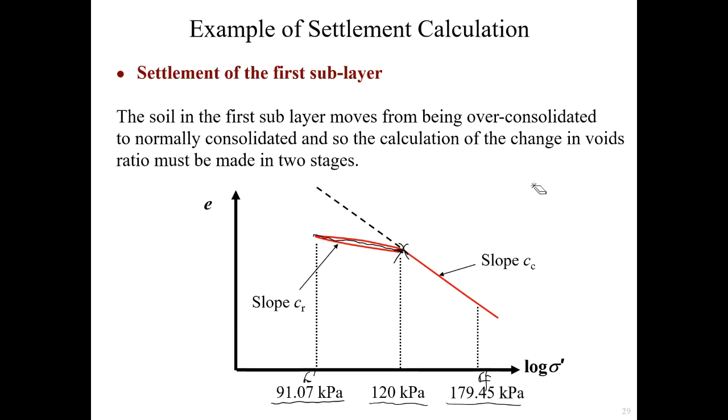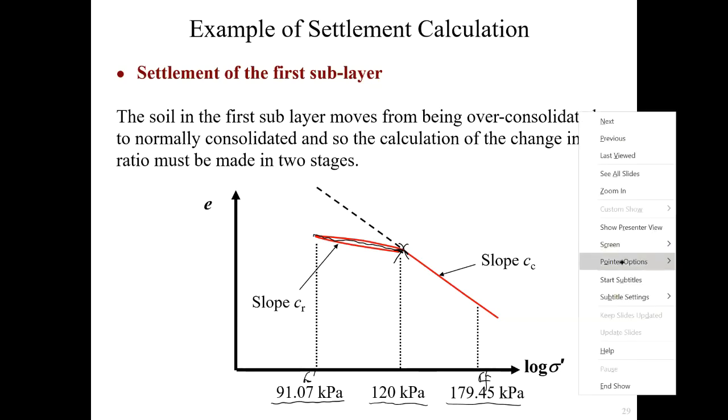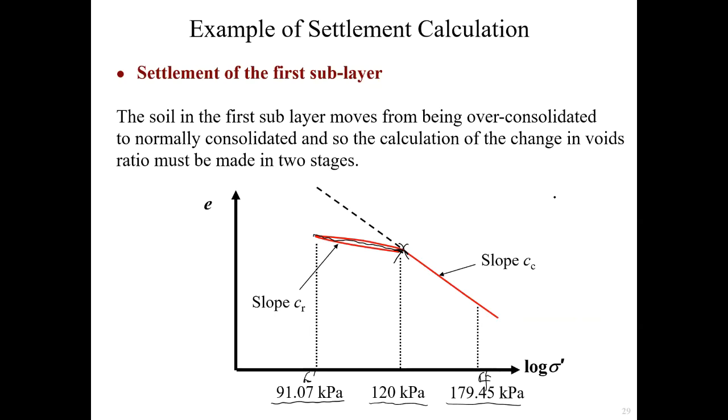No, you see, for all these problems, one is the normally consolidated. Normally consolidated, the gradient is always greater than the over-consolidated. So when you just have an assessment, you always plot the 2 curves in this way. This is for NC, this is for OC. So this is sigma P prime, this will be the sigma F prime, and this is the sigma O prime.